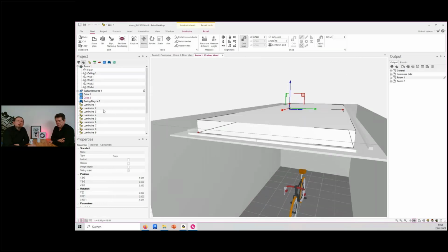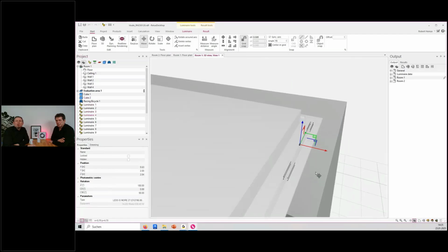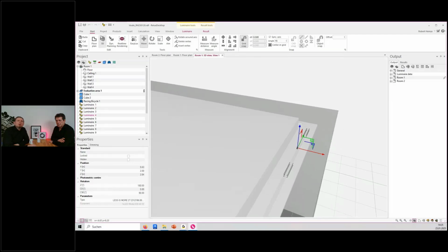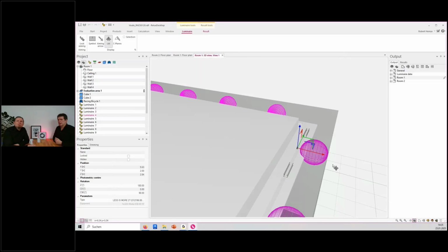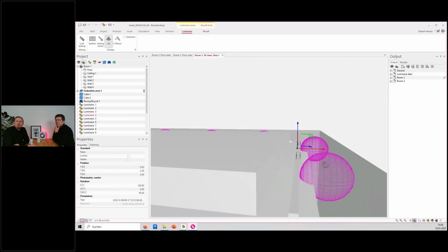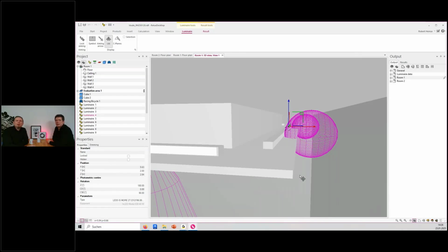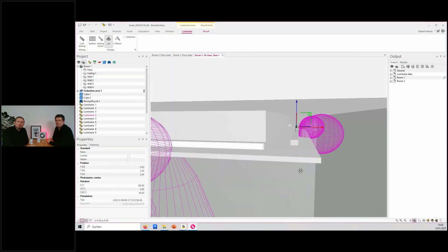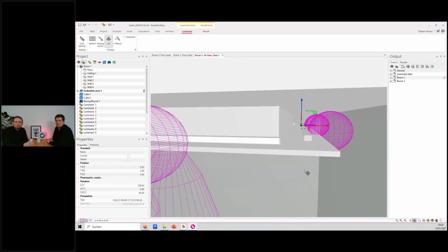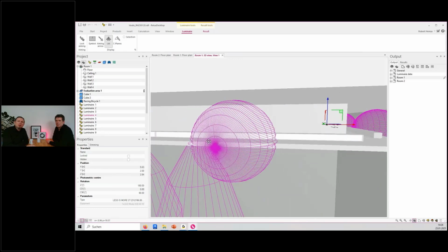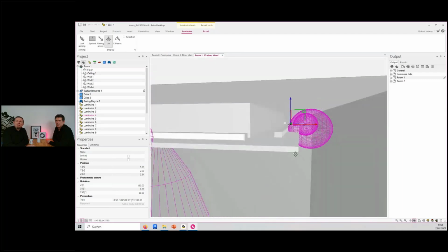And on this construction, I have just put luminaires, some free illuminating luminaires with more than Lambertian LDC. Classically, this is directed upward, but this has not really an effect because you have round tubes or something which sends the light to all directions. It should not be focused light or pointed light or within a direction. It should just glow in all directions. This would be the best. So Lambertian luminaires are the best, and the effect is quite nice.